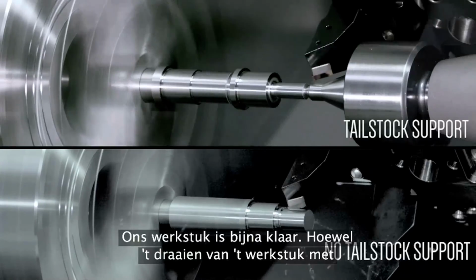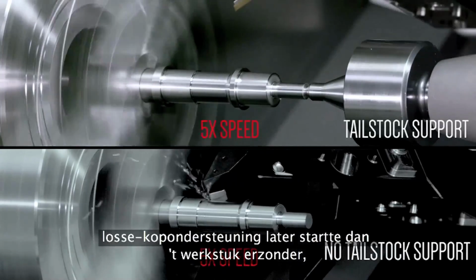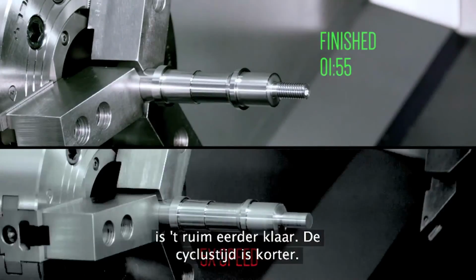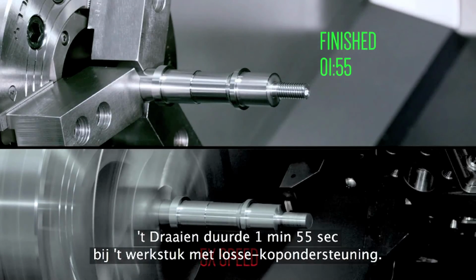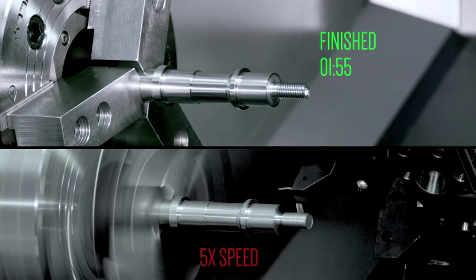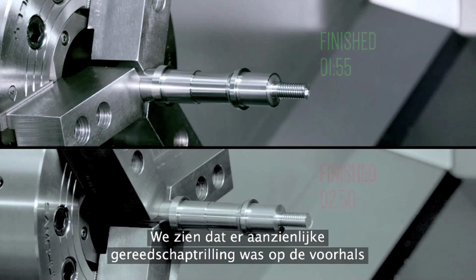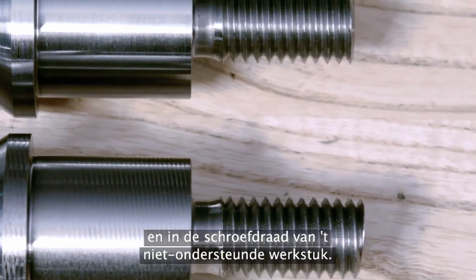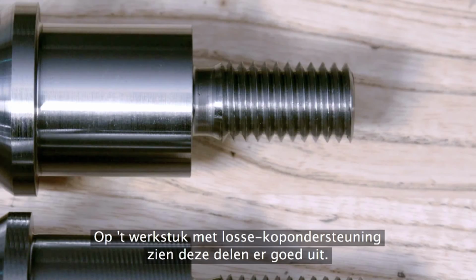As our part reaches completion, we can see that even though the tailstock supported part started cutting after the unsupported part, in the end, it finished well ahead with a lower cycle time. It took 1 minute and 55 seconds to cut the tailstock supported part, and 2 minutes 50 seconds to cut it without a support, a significant difference. And we can also see visually there is significant chatter on the front journal as well as in the threaded section of the unsupported part, whereas the same areas on the tailstock supported part look good.